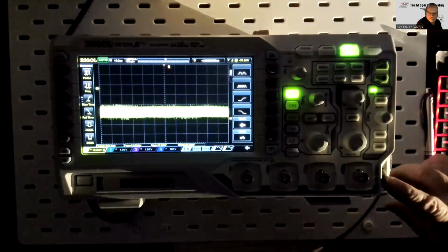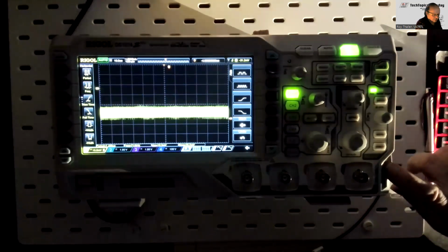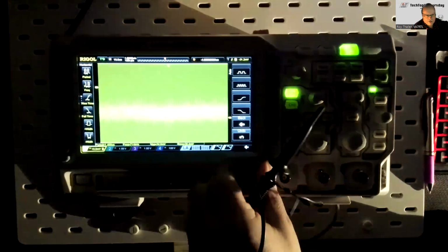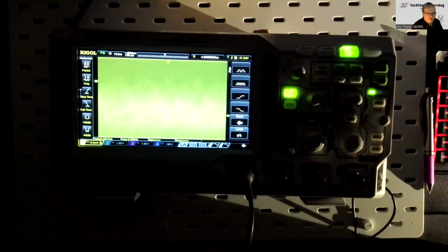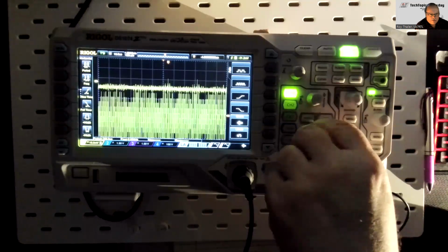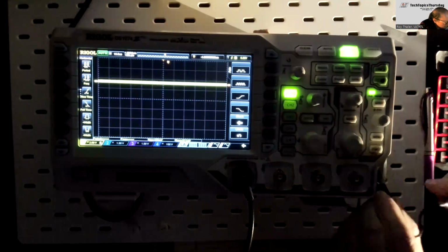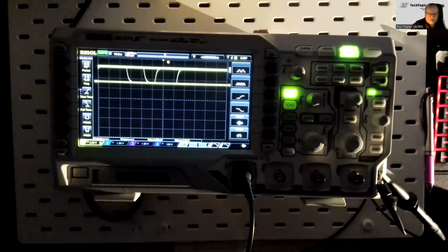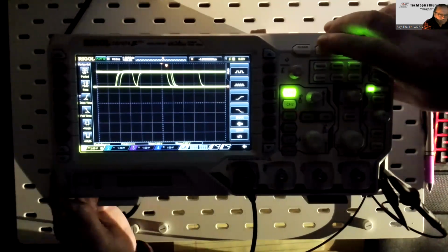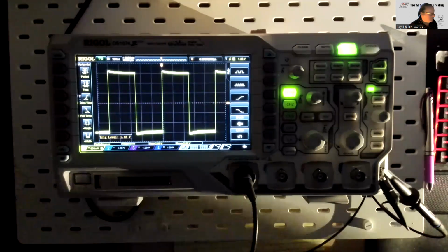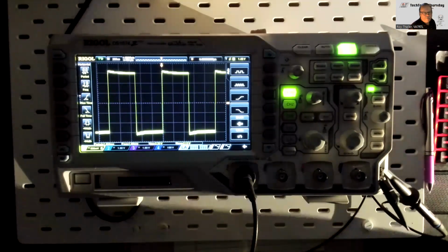Now on the side of the scope here, you have a 1 kilohertz test signal, and that's used to calibrate your probes. So what you can do is plug this into your channel. As you can see, it's picking up a whole bunch of noise around here. You can go here and turn down the scale setting, but what you can do is hook it up to your signal, and you push the auto button again. And so it's now using a square wave to calibrate your probe.